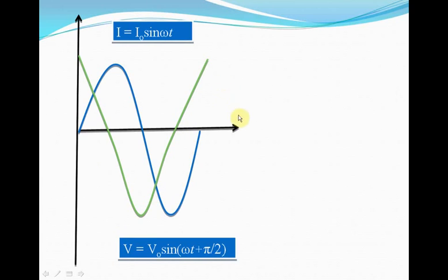If you extend this curve further, however, this same cycle starts later for the current. It starts here, isn't it? The green curve attains this lower depression earlier, and the blue curve attains the lower depression later. So the blue curve lags behind the green curve, or the current lags behind the voltage, which is true. The current in an inductor lags behind the voltage by pi by 2.